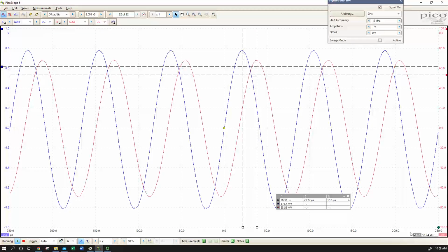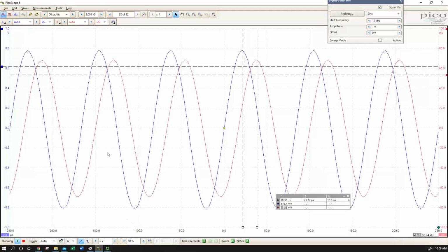So far, all of our exercises with the oscilloscope have been time-based. I'm waving my cursor back and forth, and we're looking at time on the x-axis. So we're looking at the amplitude of some voltage signal as a function of time, and we're capturing the waveforms by sampling at a particular rate. That's how an oscilloscope shows us these beautiful static waveforms for something that's actually changing very quickly. In our case, that is changing at 12 kilohertz.